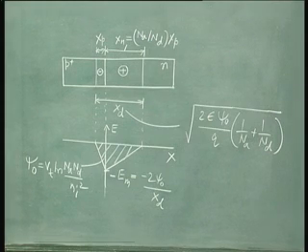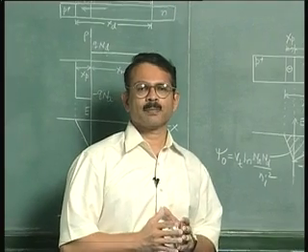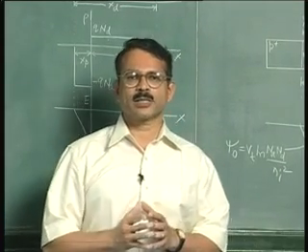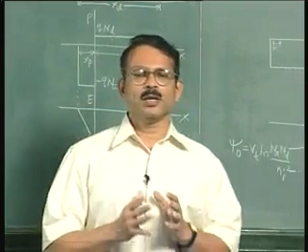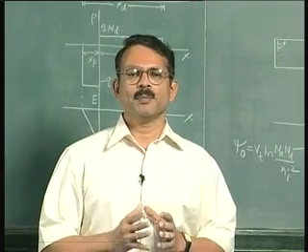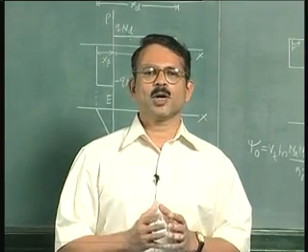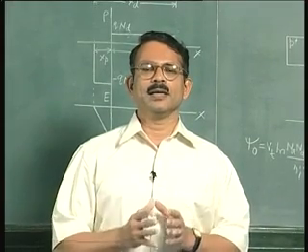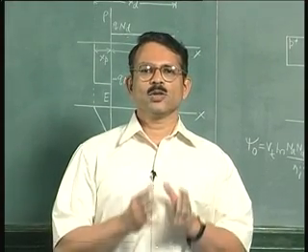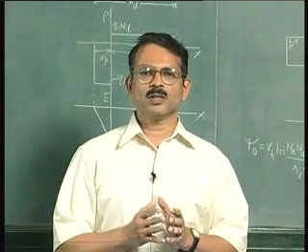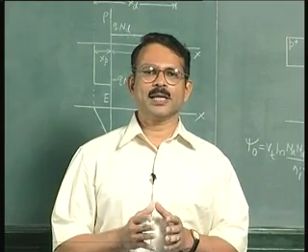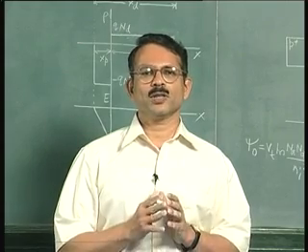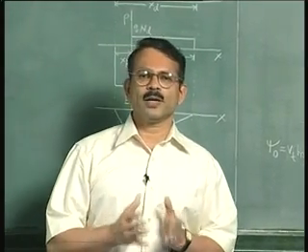So this is how, starting with the basic equations of transport and continuity and Gauss's law, we have derived all the information. Note that continuity equation was not used because it is trivial in this case, because every term of the continuity equation on the left hand side and on the right hand side is 0. There is no rate of change of carrier concentration, there are no excess carriers, and there are no currents. Therefore, continuity equation was not necessary or not useful at all in this analysis.